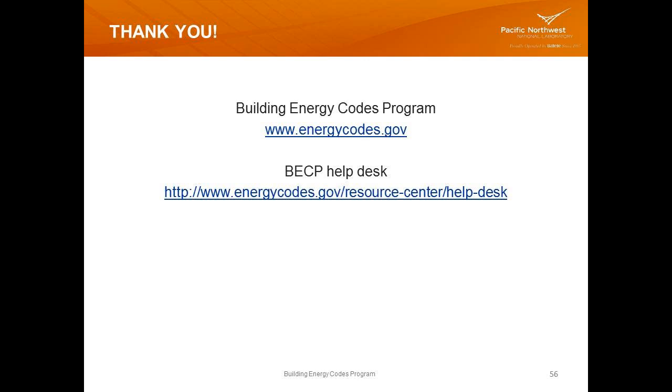It's your choice. However, you can't mix and match. You cannot do your envelope using 90.1 and do your lighting using IECC. It's one or the other, and it's all for the entire building. You cannot mix and match between these two codes, and that's written in the code. So once you go down the route of 90.1, then you better communicate with all the rest of the people on that project that they have to use 90.1 too if they're doing separate compliance reports for the lighting or the mechanical. It's one or the other.